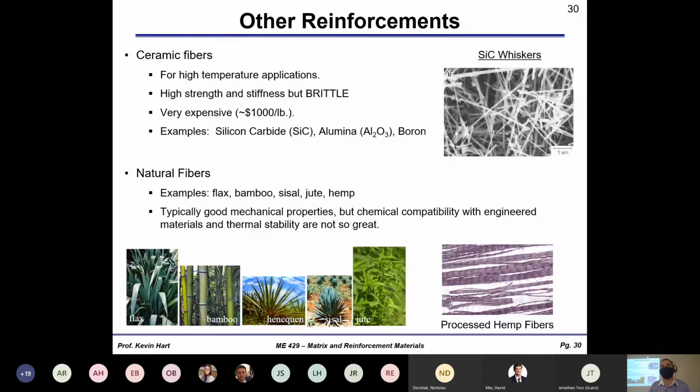So they're in the natural world and they're very useful. Now the issue is that the natural fibers that might make up jute or hemp or basalt or whatever generally don't have any reason to bond to, let's say, epoxy. The surface of a hemp fiber isn't chemically favored to bond to an epoxy for any real reason. It's chemically favored to bond with other living things like the lignin in the trees. So when you're thinking about using natural fibers, it's actually hard to make a nice interface between the natural fiber and your matrix material, whatever the matrix material might be.